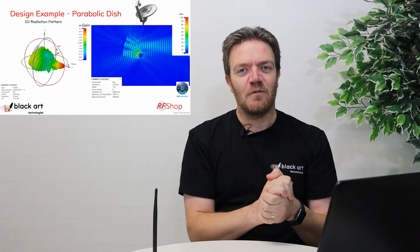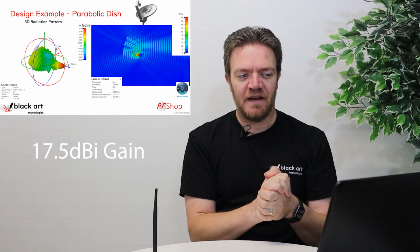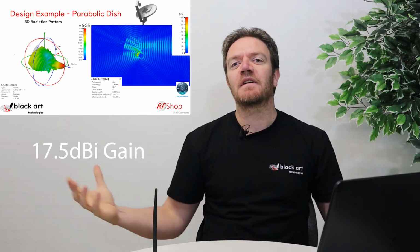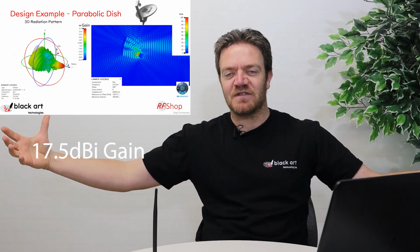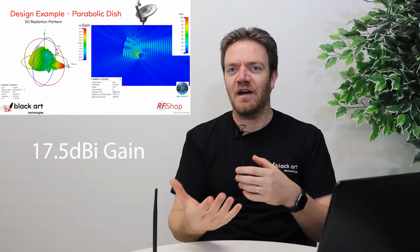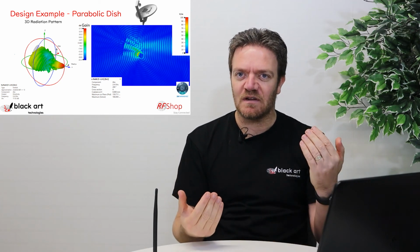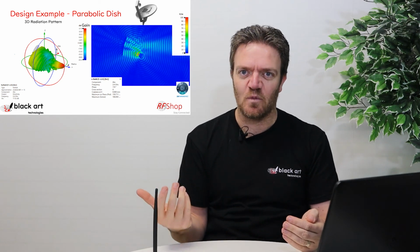At the end, with all the cutting away to make it more practical, I end up with an antenna that is now 17.5 dB gain. Of course, it's 10 dB lower than the perfect ideal dish, but nobody wants a big 1.2 meter dish on their roof if they want TV antennas. You want something smaller, so you have to come to a compromise. That's why cell phones don't have external antennas anymore. We come to a compromised outcome, matching the customer's expectations, plus trying to get the technical expectations working good enough as well.